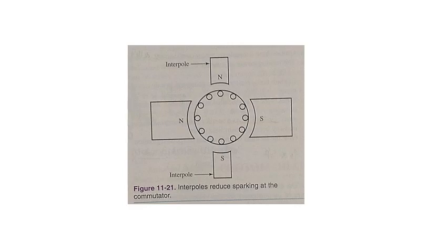With this method, the brushes are moved slightly against the direction of rotation, and the counter EMF is used to induce the previous pole. The counter EMF opposes the self-induction caused by the decreasing current in the coil, and sparking is limited. This method, however, is not practical for preventing sparks on large motors used in a varying load condition. As the load varies on the motor, the brush position must be changed by hand. Instead, larger motors use interpoles to reduce the sparking.